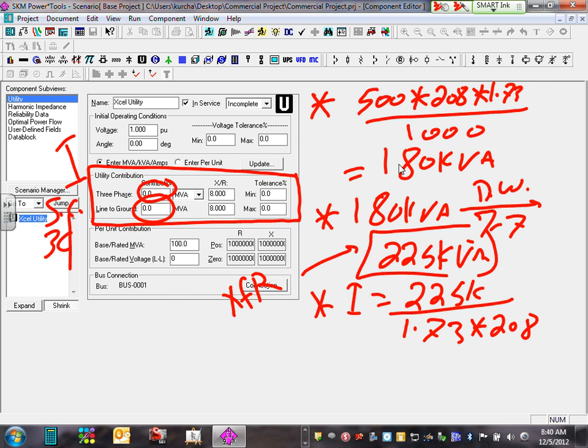What is the page that I used? Page 424. 424. All this, guys, is just to come up with a little number here, and you only do it one time for the utility. This is 424. It has already been done for me, so this will be my full load amp, 625 equals 625. Cool. The last thing you need to do is I short circuit equals 625 divided by the impedance.